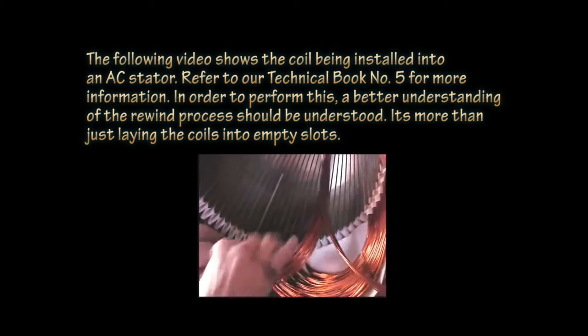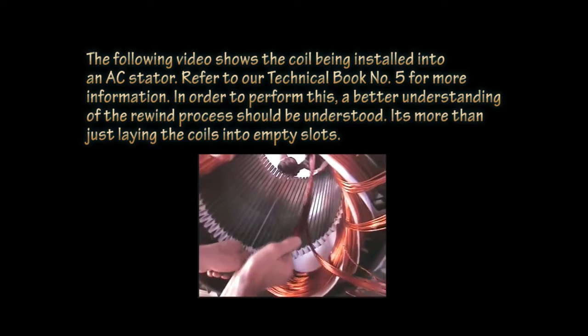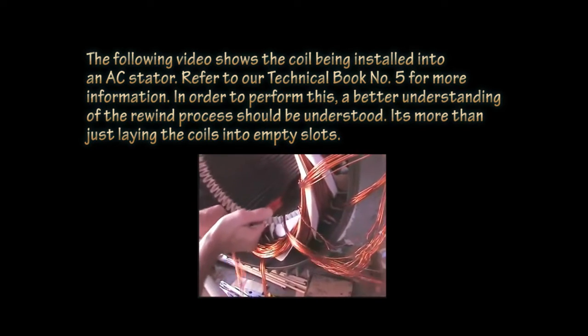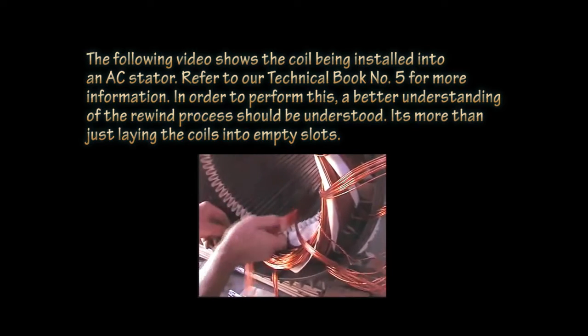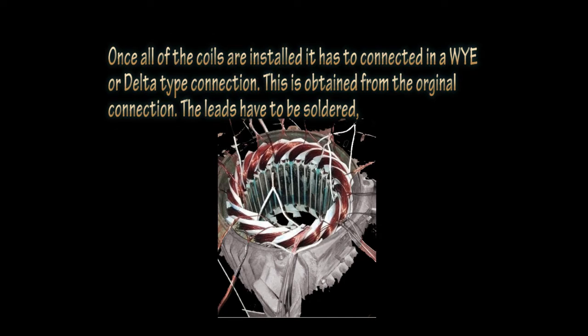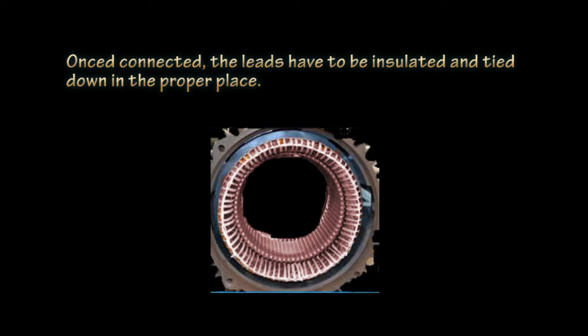Refer to our technical book number 5 for more information. In order to perform this, a better understanding of the rewind process should be understood. It is more than just laying the coils into empty slots. Once all of the coils are installed, they have to be connected in a Y or delta type connection. This is obtained from the original connection. The leads have to be soldered. Once connected, the leads have to be insulated and tied down in the proper place.